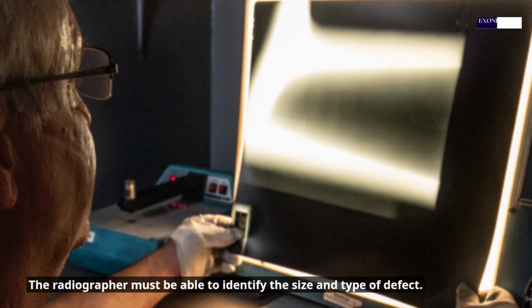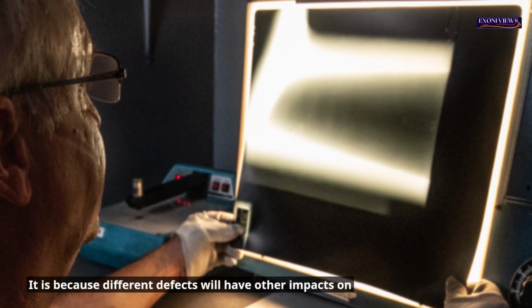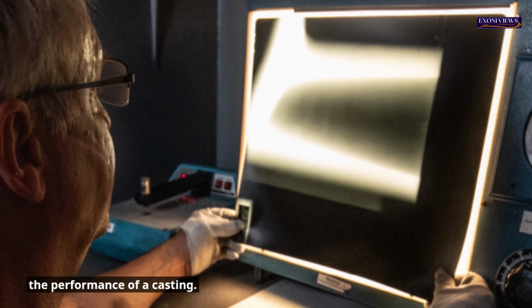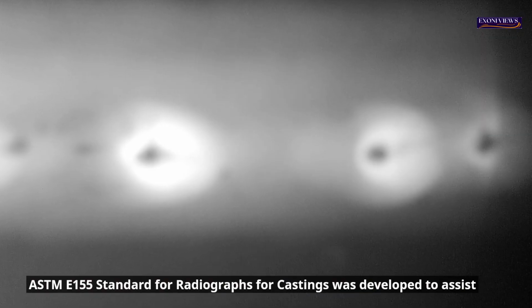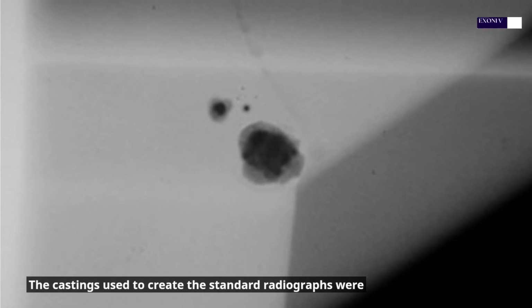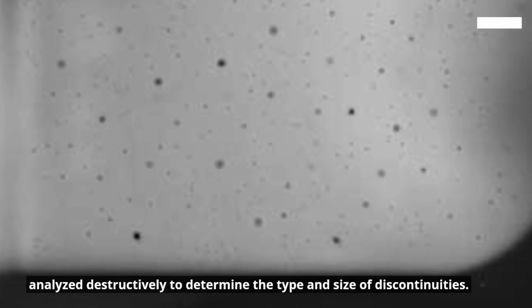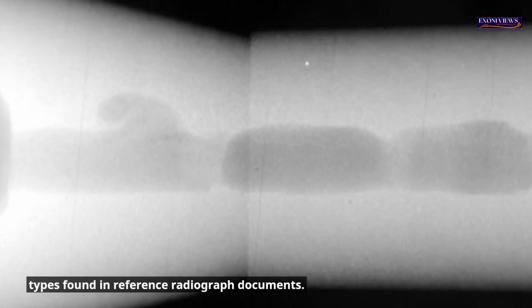The radiographer must be able to identify the size and type of defect, because different defects will have different impacts on the performance of a casting. The ASTM E155 standard of reference radiographs for castings was developed to assist the radiographer in assessing the flaws present in the component. The castings used to create the standard radiographs were analyzed destructively to determine the type and size of discontinuities. Here is a short description of the commonest discontinuity types found in reference radiograph documents.